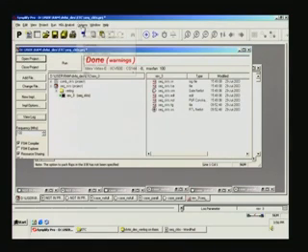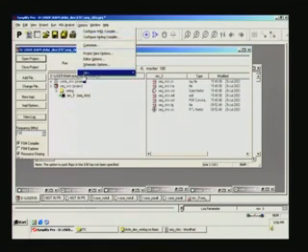So, just click on that options, then at the tail end you will have Xilinx, and once again within Xilinx you move on to this, you have start design manager, start floor planner, then start ISE project navigator, and in Xilinx place and route the design manager does not seem to be coming in the recent revisions, only project navigator is available. So, but I am going to show you on design manager because you can get a more feel than the project navigator, and it should not be difficult for you to migrate from design manager to project navigator. What all you need is a couple of hours of familiarity.